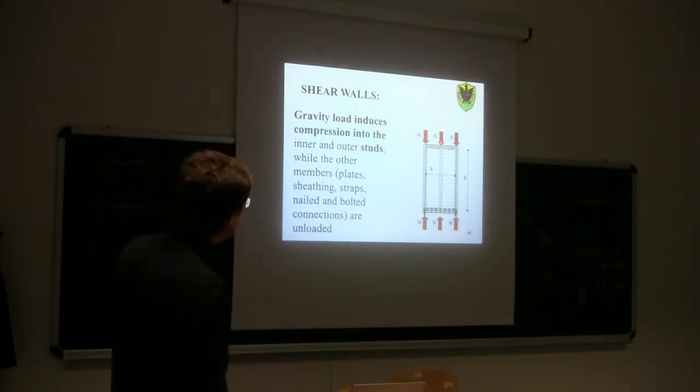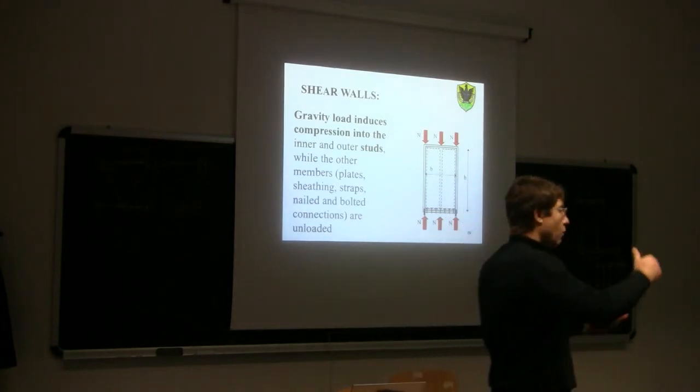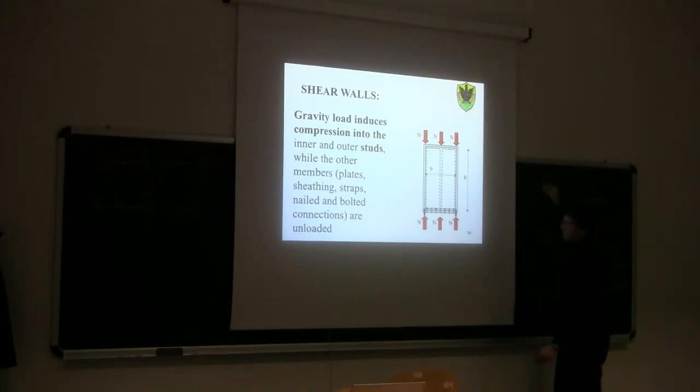Those joists will be above the wall, and will transfer the vertical load N to the wall underneath. Of course, not only the joists, but also the wall which is on top of the joist. So, we said before, in the platform construction, you have a wall, then above the wall you have a joist, the floor, and then above the floor you have another wall. So all the vertical loads coming from the wall and from the joist will be applied on top of the wall.